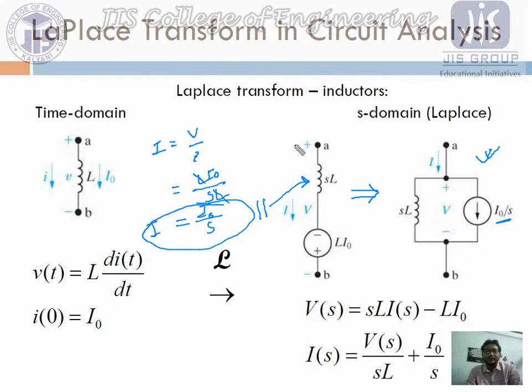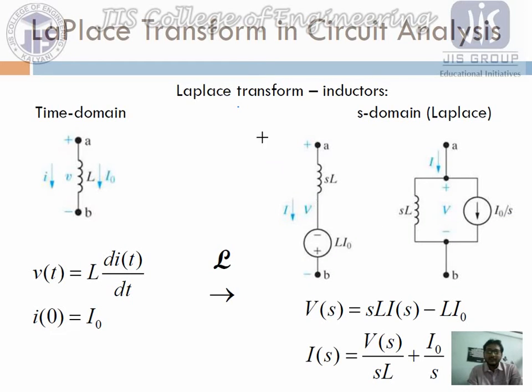Okay. So be careful. So we can write for our further use. Let me erase it first. If there is any inductor, so for inductor, not Laplace sign, we can simply write one source, the source value, that is L I0.